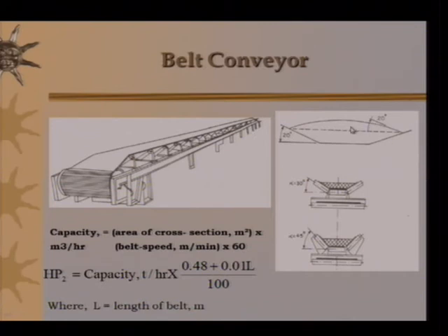is the belt which has been put at an angle, and you see there are idlers here on the right and left. In order to increase the capacity of transportation on the belt conveyor, you can change the angle. See here, angle 30 degrees or angle 45 degrees, depending on your requirement. Now these idlers are not powered, only the bottom portion is powered from the motor, and the material is conveyed on the belt conveyor from one point to the other.